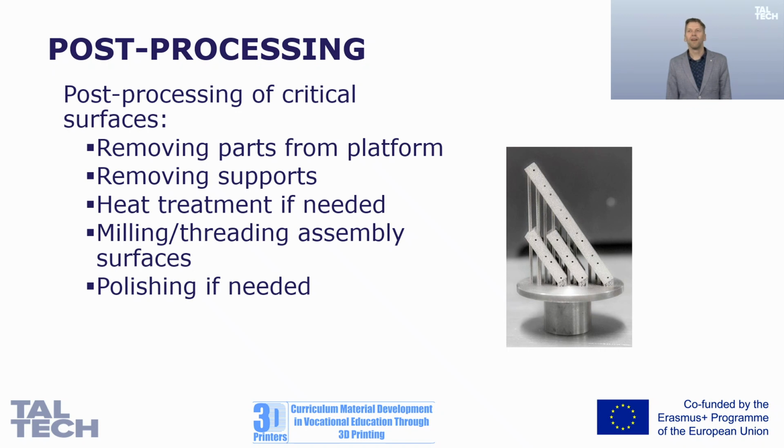And also the supports leave marks on the surface. So we have to post-process these surfaces too, which in the case of more complicated parts can be quite a challenging task. But typically CNC milling technology is used for that.